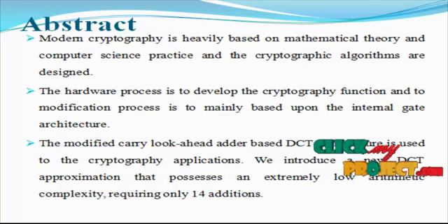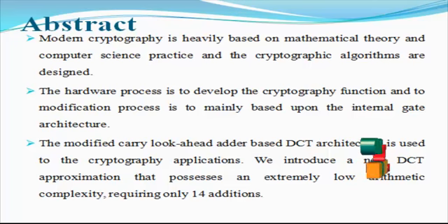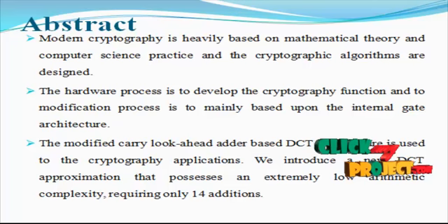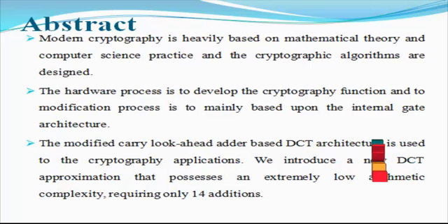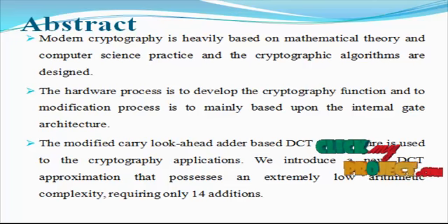Video processing systems such as HEVC require low energy consumption. The multimedia market has led to extensive development of fast algorithms for the efficient approximation of 2D DCT transforms. The DCT is employed in multimedia compression standards due to its remarkable energy compaction properties. Multiplier-free approximate DCT transforms have been proposed that offer superior compression performance at very low circuit complexity.